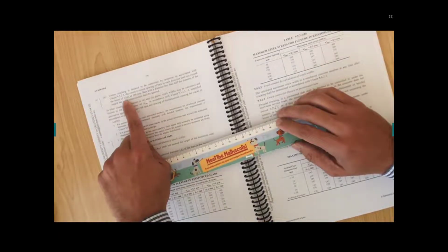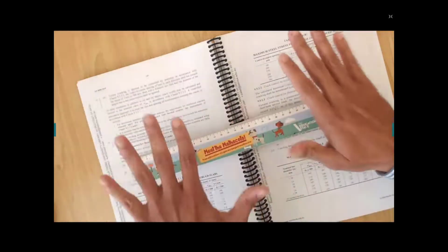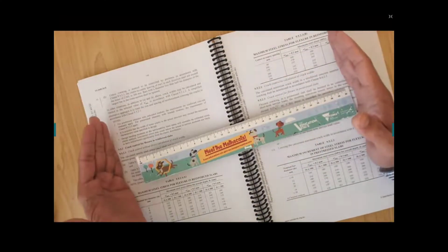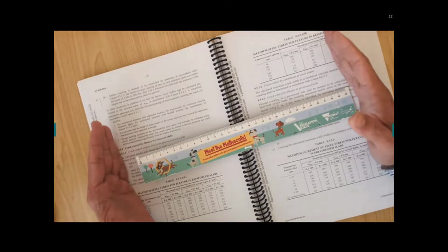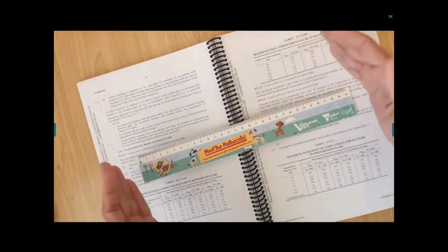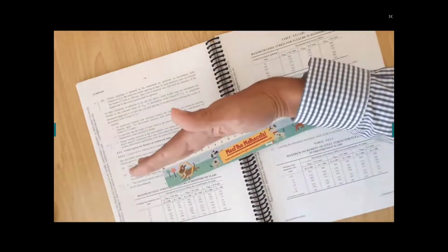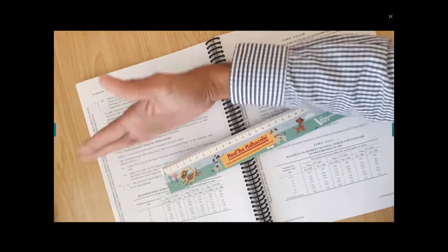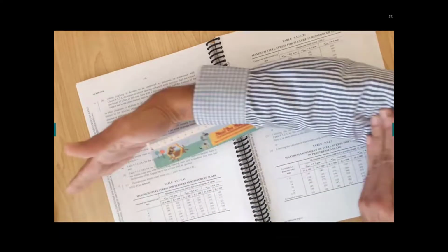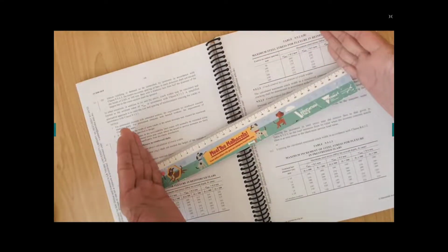Why? Because you can look at that 300. If you have 160 millimeters, that becomes 320, and they will prevent you from doing this. There is no design of the slab that tells you to put the bar 400 millimeters apart. If you do, the slab will bend and cracks will appear. To stop that, you need this limit. Just like one hand: if you don't have a ruler, you can put your hand out about 1 foot, from this end to this hand. So when you go on site and see the slab, it should not exceed this.